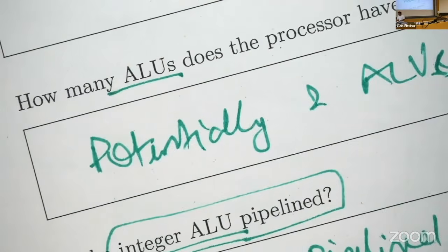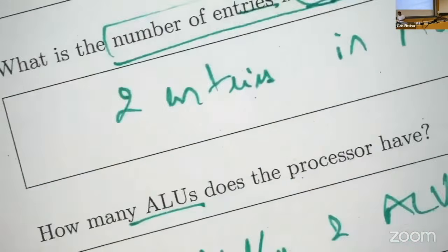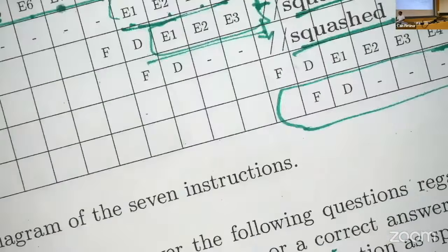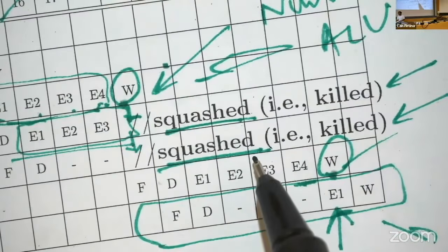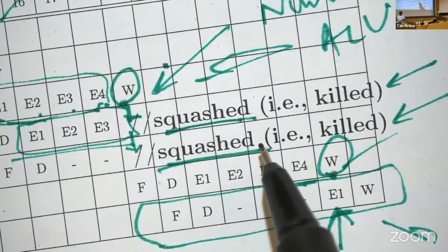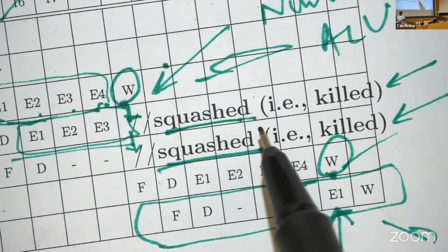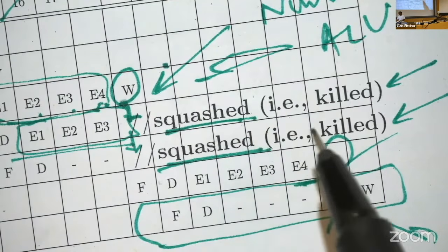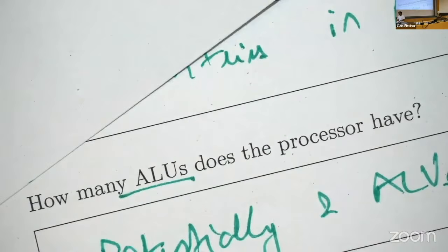All right, does the processor perform branch prediction? We saw clearly some instructions got squashed. Once again, the tip to remember: squashing means dynamic execution. Dynamic execution can come from load stores, branch predictors, load value predictors, some other arbiters, but usually it is branch predictors. So yes, we do perform branch prediction, and our branch prediction went wrong.